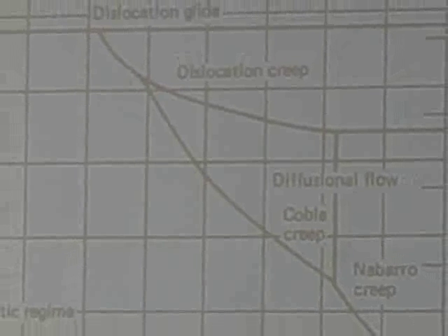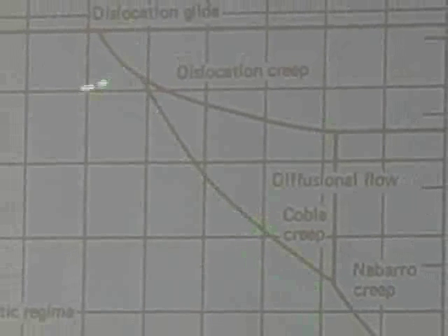He came up with these kind of broad scale ways of looking at things. This is the normalized tensile stress over orders of magnitude versus the homologous temperature, and this is a creep diagram. He had a student when he was at Harvard do a doctoral thesis on developing these creep diagrams, and I think that ended up as this book. I wish I had a copy of it, but I couldn't find it on Amazon. But the library has one for all kinds of different alloys.